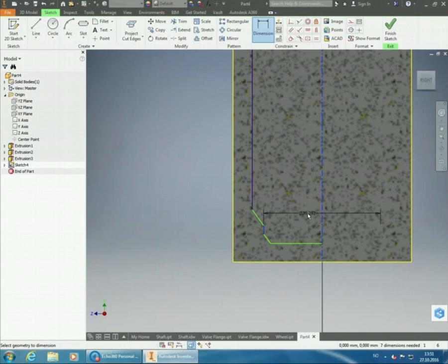And then the small vertical line down at the bottom is supposed to have 47 minus 4 minus 4. So actually we could have done this a bit differently. We don't need to put a diameter there. We can do the dimension from this line to that line instead, with 4 millimeters.